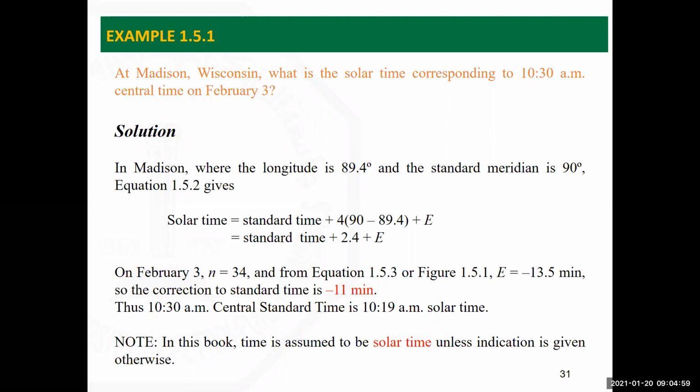What's the importance of the solar time? It would be important if we need to indicate how much solar radiation is falling onto a certain surface. Then, being able to calculate it hour by hour, we can integrate it over the day. But we don't use it, for example, to say that the class is starting at a certain hour according to the solar time; we just say that it's going to be based on the local time. So solar time is utilized only for the sake of indicating the solar radiation which is falling onto a certain surface.